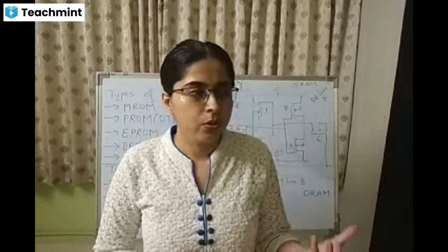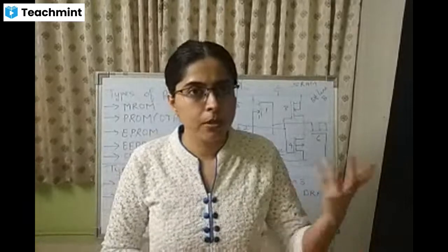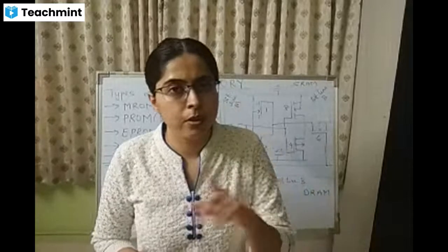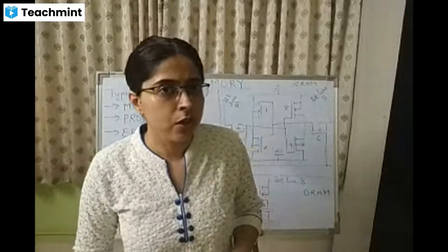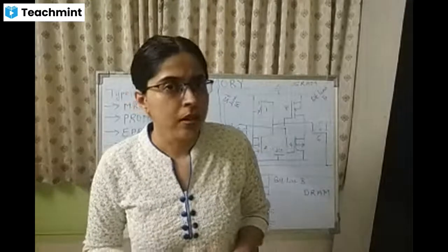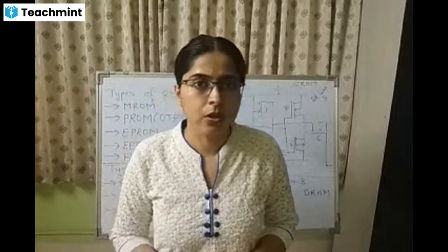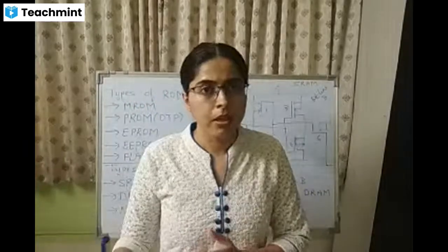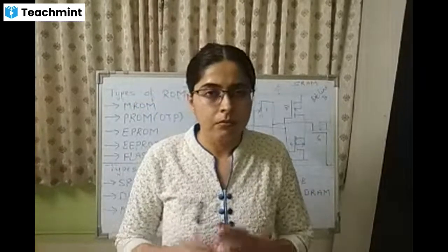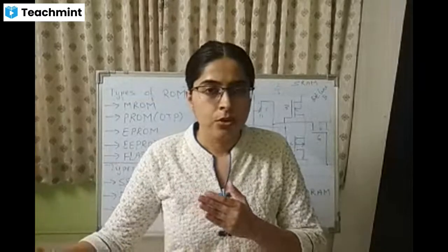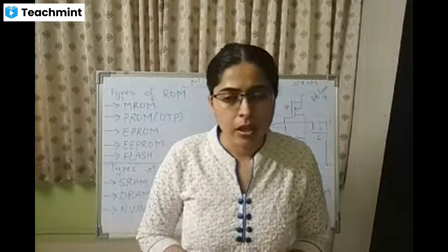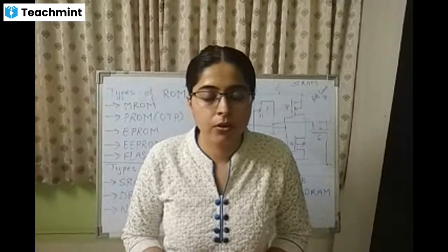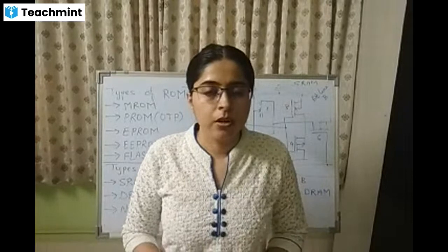Whenever you want to store a particular programming pattern of ones and zeros in the PROM, the fuses which are blown or burned represent logic 0, and fuses which are not blown or burned represent logic 1. The default state is logic 1. So we have programmable read-only memory, which is programmed by the end user. The user can program it.